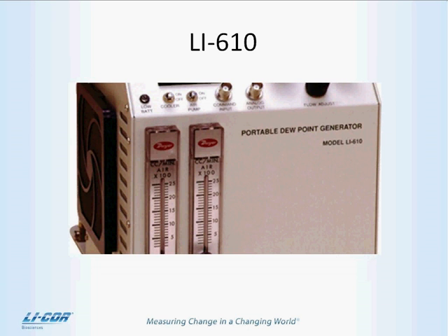On the other hand, there are a couple of cons to using this instrumentation. For one, it's another piece of equipment that you've got to use, and you've got to make room for it wherever you're doing your measurements, and you've got to make sure everything's fine. For another, if you have both the 610 and the LI-6400 on the same AC circuit, you can end up with a little bit of a ground loop, which can cause noise in both of them, and you want to avoid that.